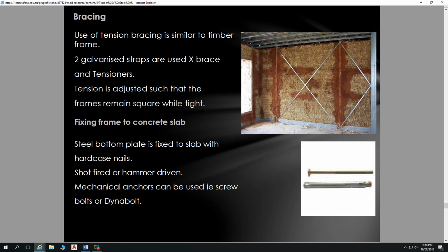So there are certain edge distances you've got to think about when you're specifying bottom plate fixings. Whereas chemset anchors have far less required edge distance, because you're drilling a hole, putting the anchor in, and gluing it in.